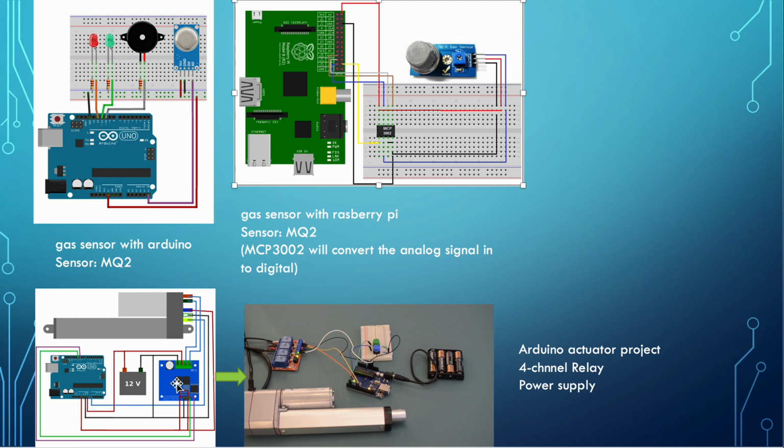This example is there mainly to show that, while Arduino can give a 5-volt output, some devices, as in earlier examples, need more power than that. At that point, we should have relays and external power sources, either batteries or direct power, connected so that the actuators give the output that we want.